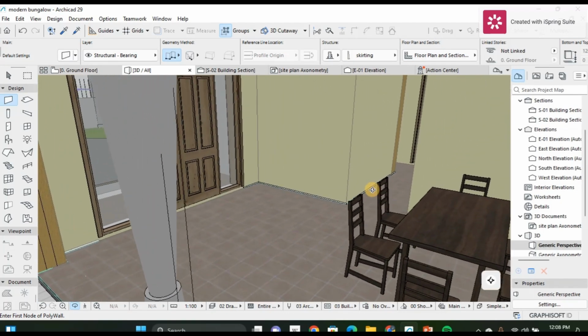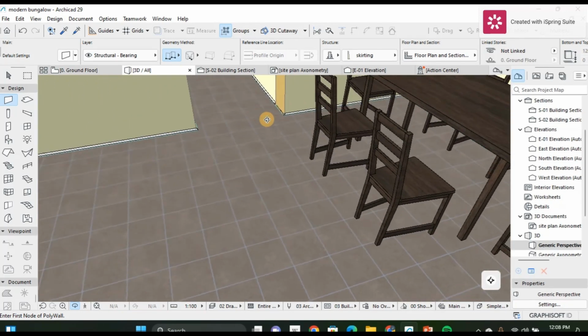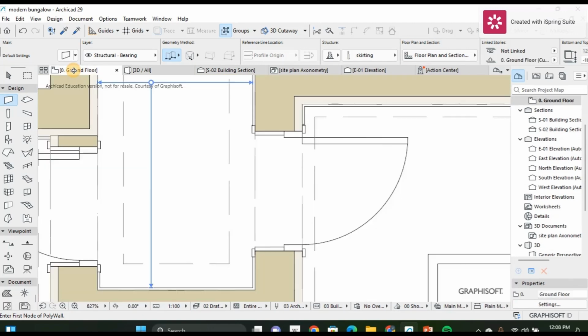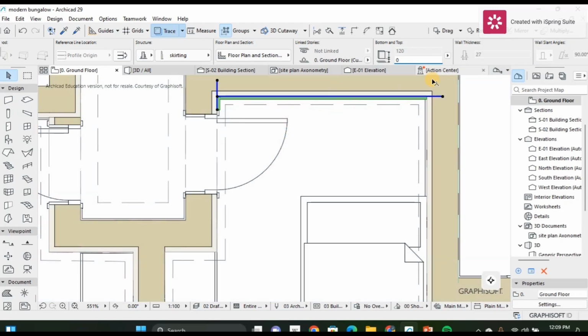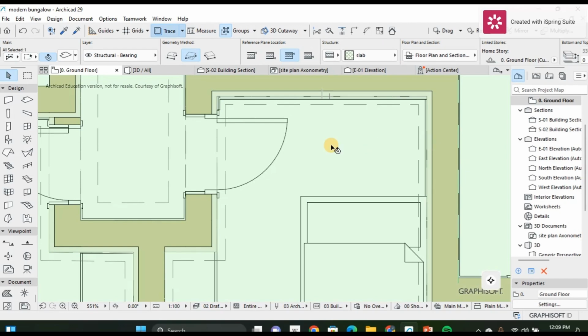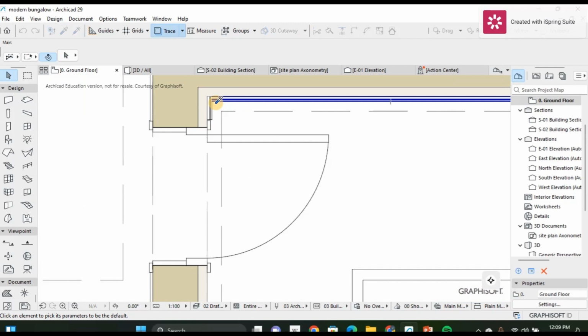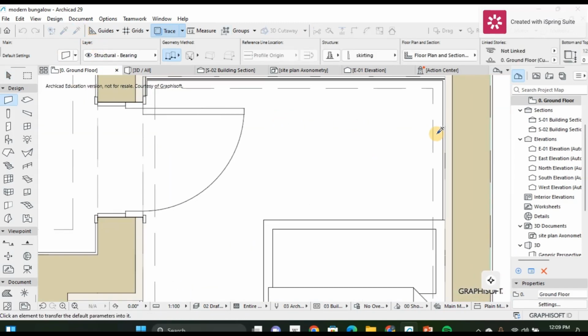The wrong thing I've done actually is I've made the skirting go downwards because it was at negative 100 and I still left it at that point. So let me just do this. I'm going to change the height of one of the skirting to 0, and then I'm just going to pick attributes from that cut and inject them on the other ones that are a bit lower.